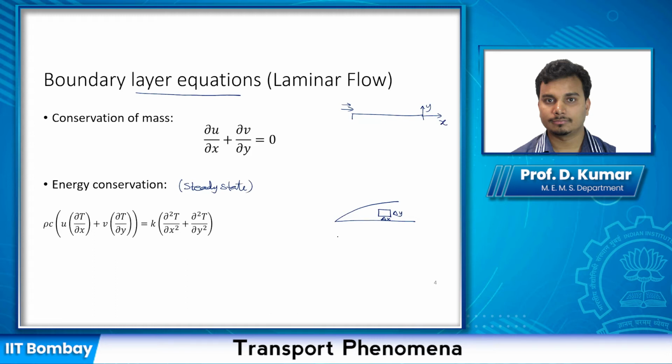So heat coming in, heat coming out, there are 3 terms. But the viscous dissipation term we can ignore under certain conditions. So there will be one Q in, and Q out term, that will be conduction. So conduction through this face and this face coming in, and this face and this face going out, and then you will have another term, advection, because of the bulk fluid flow. So the advection term will again be from here coming in, and then going out.